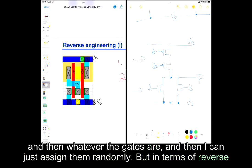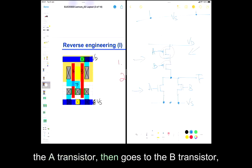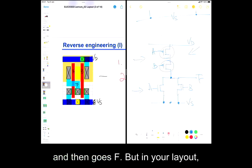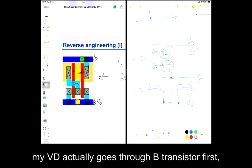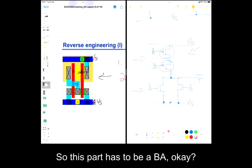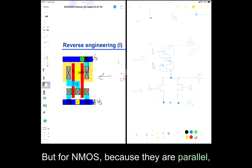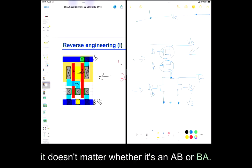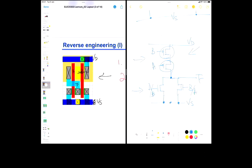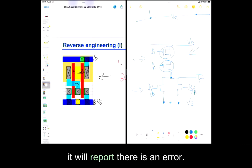But in terms of reverse engineering, you have to do an exact translation. So if this is the case, my VD first passes the A transistor, then goes to the B transistor, and then goes to F. But in your layout, my VD actually goes through the B transistor first, and then to my A transistor, and goes to F. So this part has to be a BA. But for NMOS, because they are parallel, it doesn't matter whether it's AB or BA. You can literally swap them around. So if I did what I did in my Cadence layout, it will report there is an error.